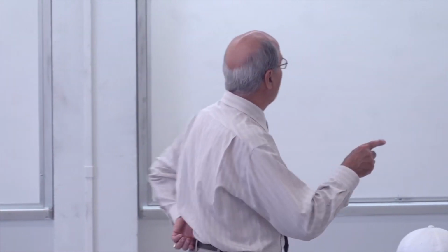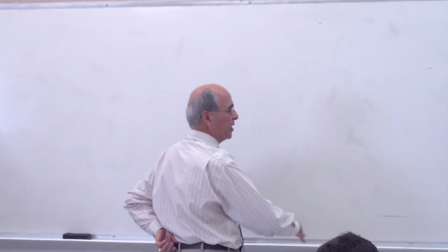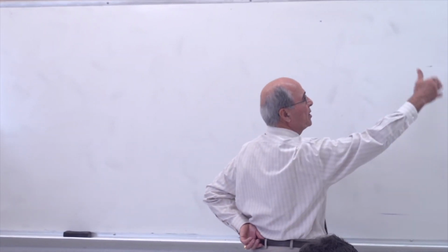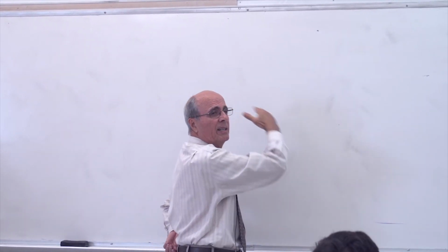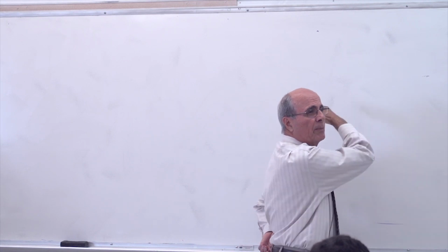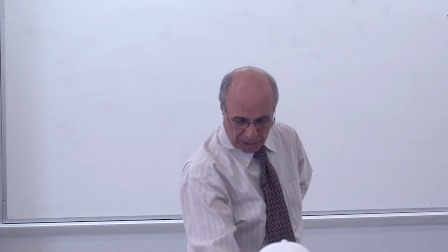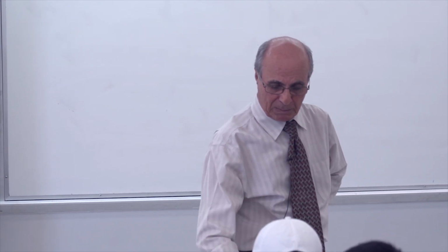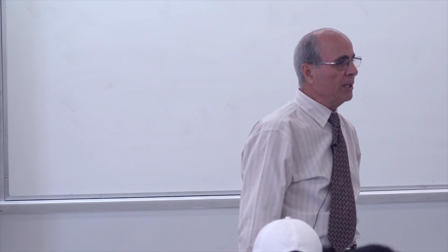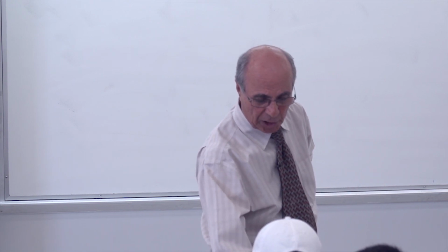The next one, in one of the questions, there is a plate like that. It is 8 feet here, 6 feet or 4 feet there, and sometimes they ask you to calculate the change in that diagonal line from there to there. That is the one I haven't talked about, but it is in your handout. Some of you already noticed and mentioned it to me. The bottom of page 11 shows a square plate, meaning the angle is at 45 degrees, which makes the difference when you calculate the strain in that diagonal direction.